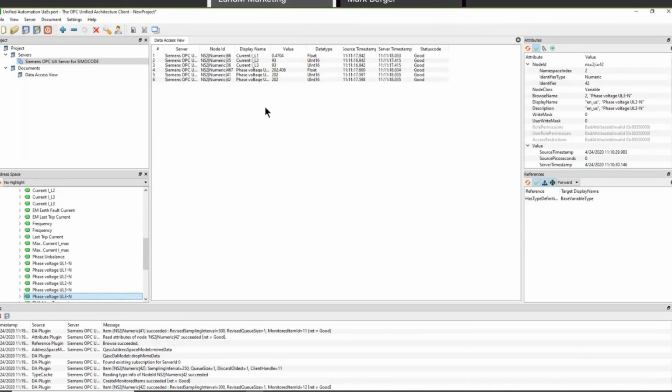These connections here then can be pulled up into your cloud. This is a great historian way of showing how the process is working. Maybe process creep could be shown here too over time. Your historian or your cloud will be monitoring this at an interval that you set, maybe a sample per second or a sample every one minute. If it's a big thermal system that you really don't need to sample every second, maybe just every minute would be sufficient.